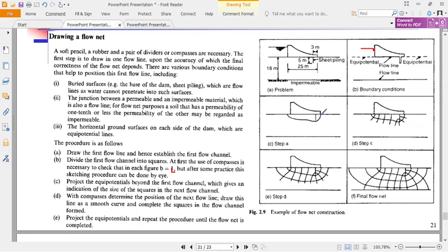So the next step is to divide this to approximate with the points of equal potential. For this one here, you draw this, so this length here is equal to this length here. You come and divide it. The next division here should be equal to this, using a protractor at 90 degrees. The first point here should be 90. Go to the bigger one.